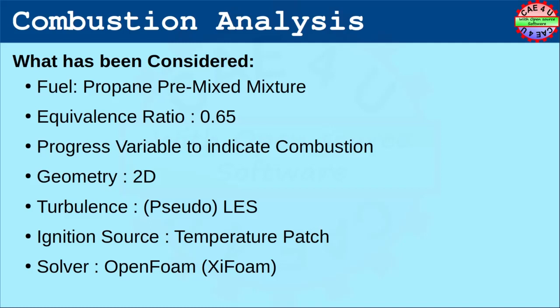And of course, for the same computational reasons, we will not consider detailed chemistry, so a progress variable is used to capture the combustion process, and the simulation was carried out only for a limited time, that is, it has been calculated only for 20 milliseconds. The XiFoam solver in OpenFOAM supports this kind of analysis, and hence XiFoam will be used for this analysis.